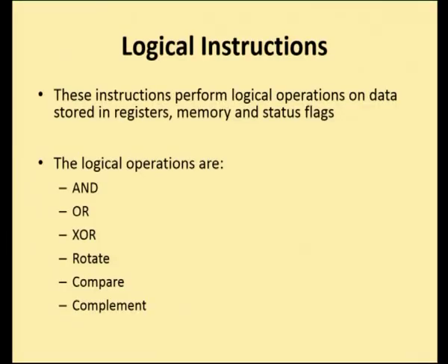In logical instructions, we are doing logical operations with basic gates, exclusive OR gates, rotate operations, complement. So, logical instructions are performed with the accumulator. One of the data should be loaded in the accumulator, another data may be in a register or memory, or it may be immediate data. These are the bitwise operations logically performed and the result is stored in the accumulator.